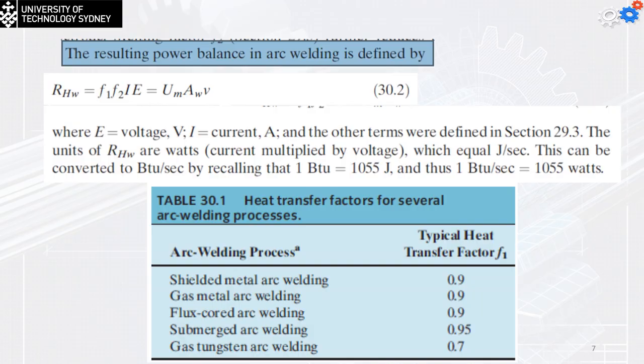Okay. Now, if you want to remember what we're doing here, I think that you have to recall the following diagram. Okay, so we have the heat source, and it's going to send the heat to the welding surface. So this is the area where it's going to have the melting process done. Some of the heat will be lost to the environment. Some of the heat will go to here, and this is where we're going to have the F1. Some of the heat will be dissipated later to the body, and this will be the F2.